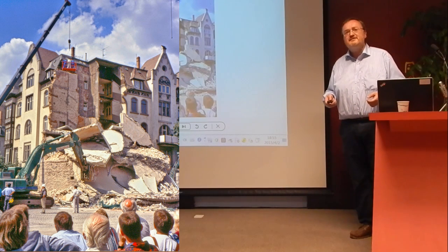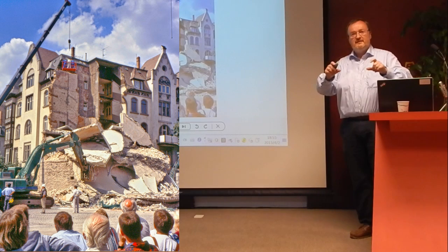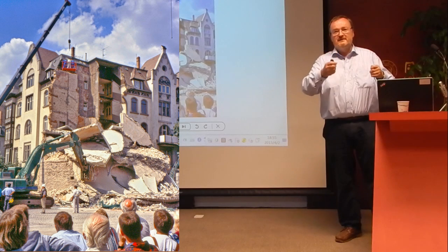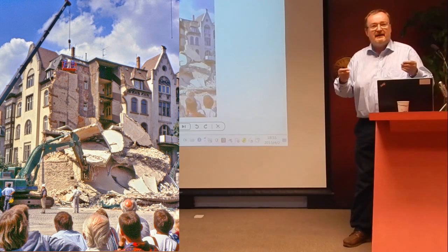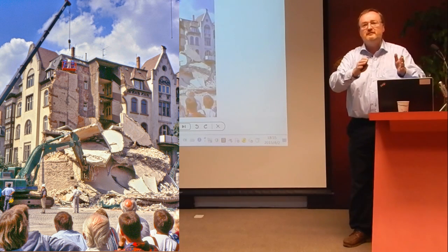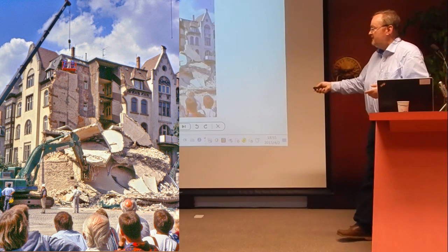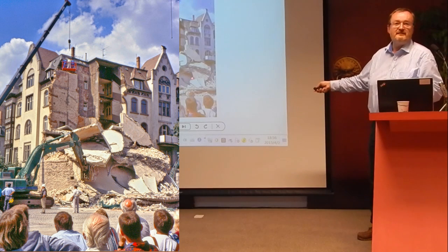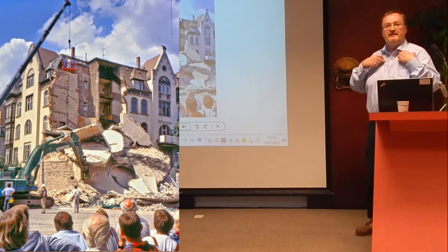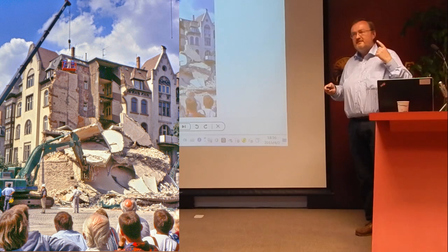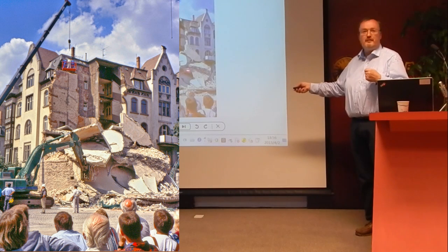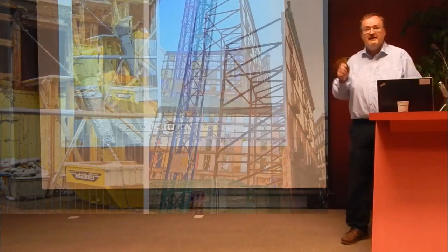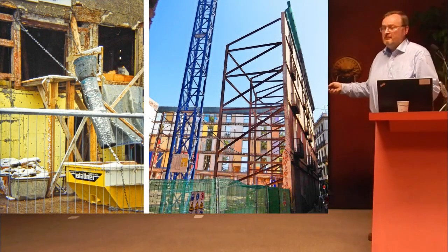And as they changed the lintels of the windows, which had been only masonry and rendering, they changed them to make it better, with real natural stone lintels. Then it all cracked down, and 4 craftsmen are dead. That is what we learned. And they had one of the most famous static engineers for this work. It's not enough only to have the numbers on the paper. You must understand. And so, what have we learned?